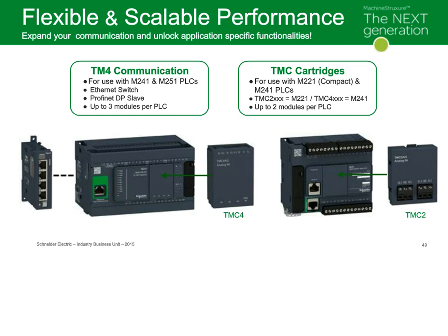Also, we added something called TMC cartridges, which directly on the front of both your Modicon M241 and your Modicon M221 PLCs, you're able to add something like a serial line or a couple of analog inputs, 12 and 16-bit resolution. You're able to add temperature inputs, all those things right to the front of the controller for around $100 list price. Very, very cost-effective way of adding some scalability and flexibility to your hardware.